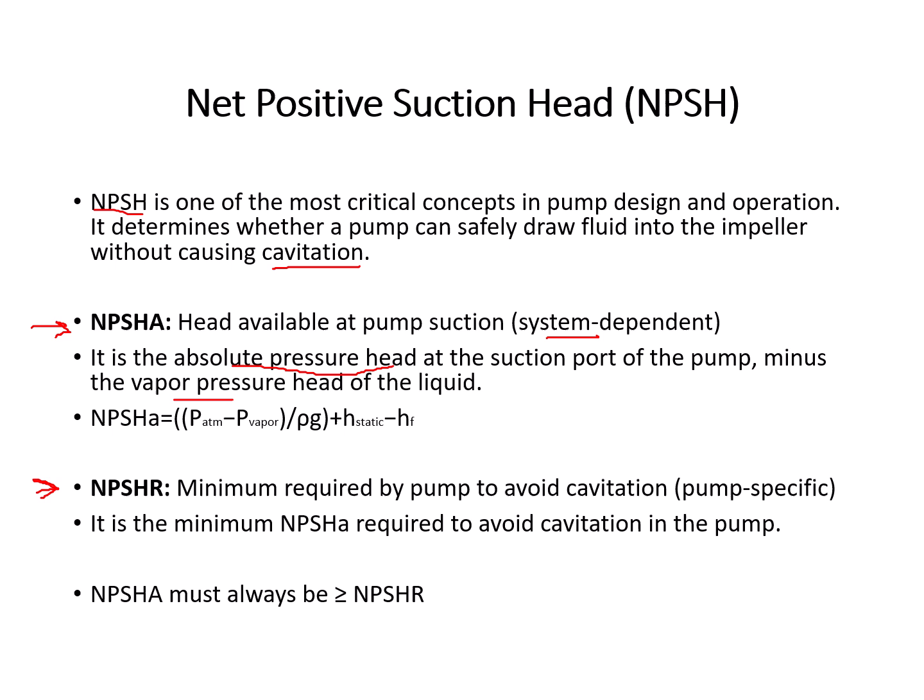Vapor pressure, you know the vapor pressure. The vapor pressure is the pressure at which the fluid vaporizes. You know any liquid vaporizes at a certain pressure and at a certain temperature. So if your pressure at the suction line drops to a point where it reaches the vapor pressure of the fluid, it will turn into bubbles, into vapor, and this will cause a lot of problems.